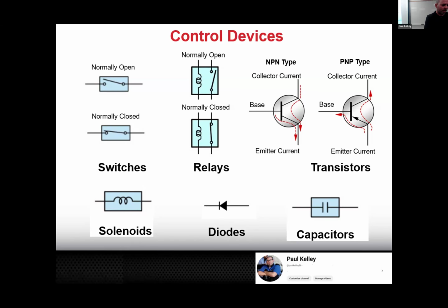So if I were to explain this relay, we've got to jump down to solenoids. But first, look at the switch side. The switch is just opened or closed, right? So just like a normal switch, if a switch is open and you want to send current to the fuel pump, you need to close the switch. And in your mind, you're thinking, oh, we need to go in here and actually press it.